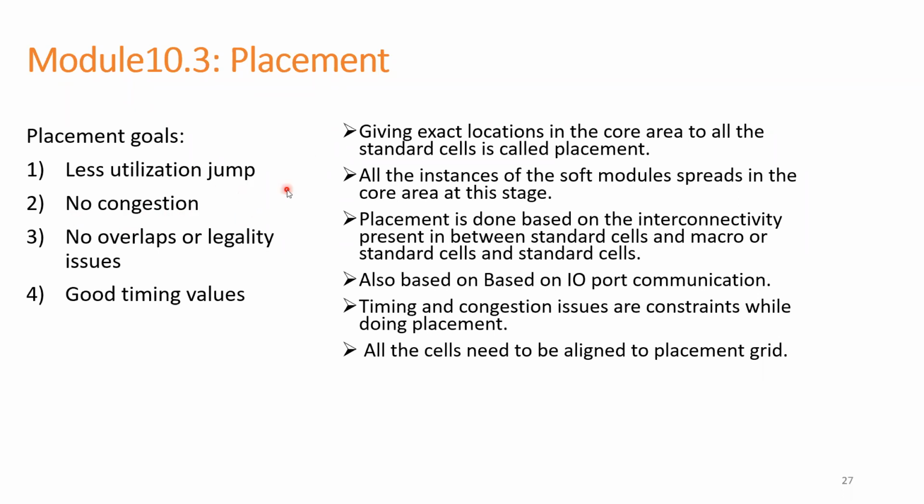There should not be any cell overlap. Cell overlap means the standard cells will come and sit one on the other, so we will call it a legality issue. So we need to legalize the cells. We need to place the cell in a legal location where there is no cell below it. So we should find the proper cell site for that, and we should place it. If we use the legalized placement type on the cells we give, the tool will automatically place the cells